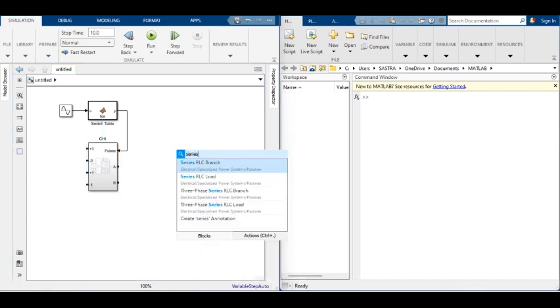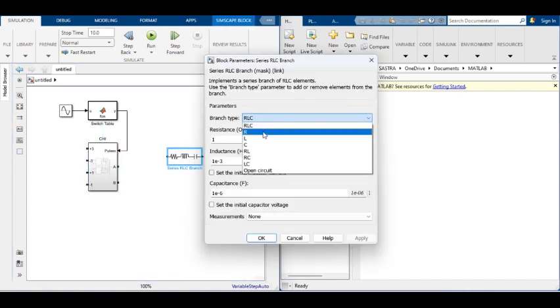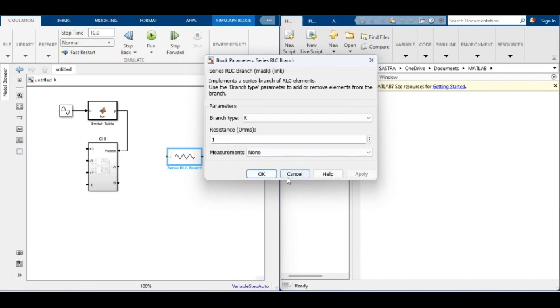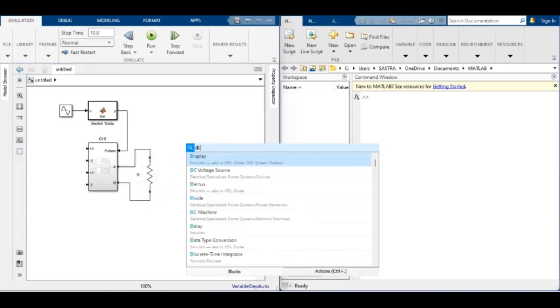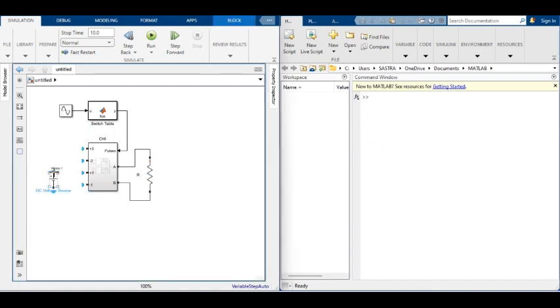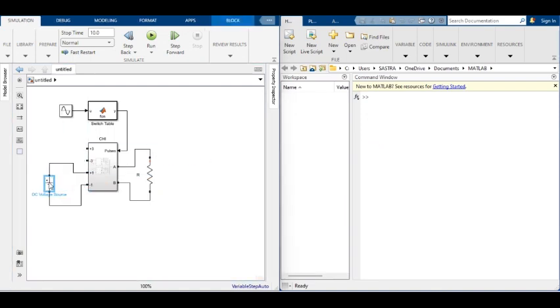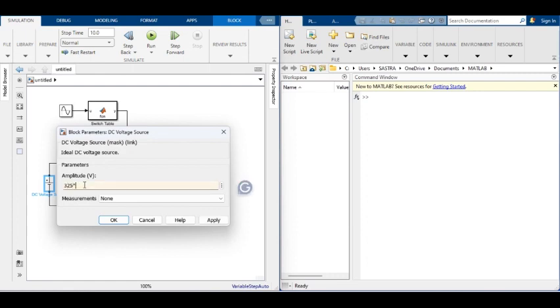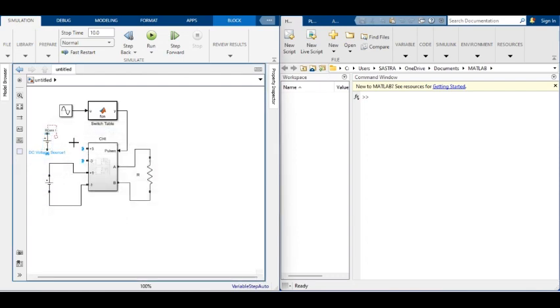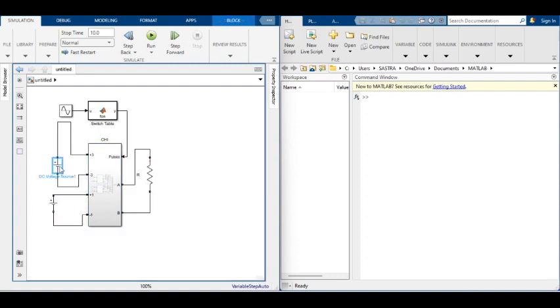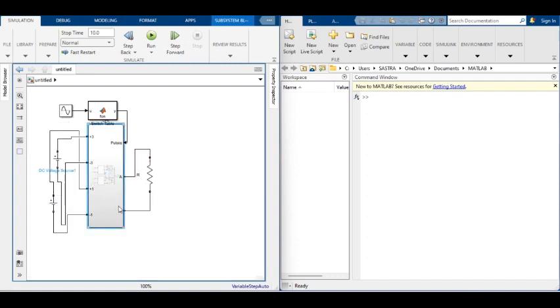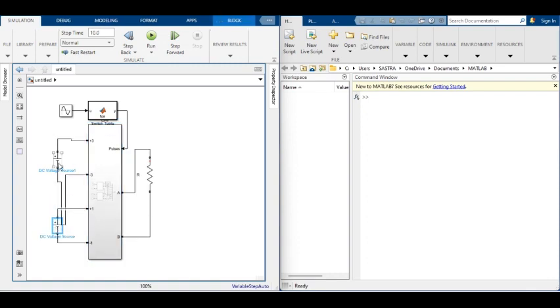A resistive load is used to see the output voltage waveform. To produce a 230 volt AC output, 325 volt DC input is required. This 325-volt DC input is split into two with the ratio 1:3. So 1 VDC is taken as 1/4 of the maximum voltage, and 3 VDC is taken as 3/4 of the maximum voltage. As a result, a 9-level output is obtained at 230 volts, 50 Hz.